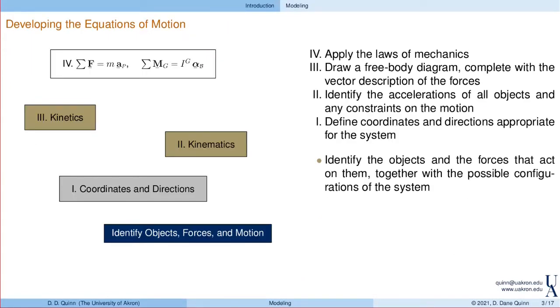Now, what about a solution procedure? Well, so in the time that I've been doing this, right, this is the framework that I have developed. And to describe this, I'm going to actually start at the end. So if I want the equations of motion, I have to apply momentum balance, right? So the last thing I'm going to do is take the sum of the forces and set that equal to the mass times acceleration, and the sum of the moments and set it equal to I alpha. And I should note that this form of angular momentum balance is valid for planar motion.